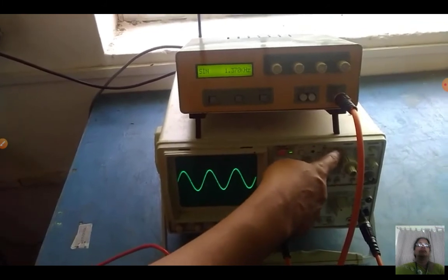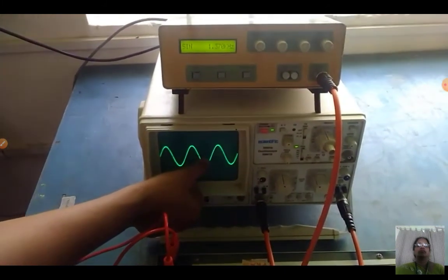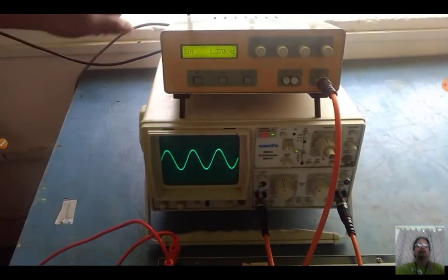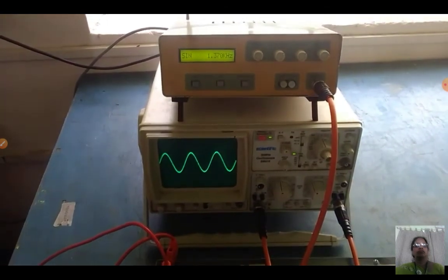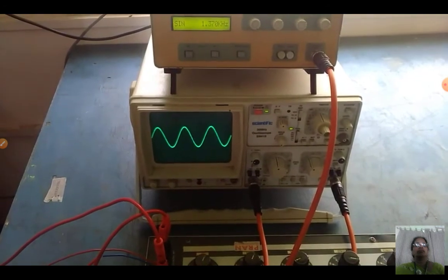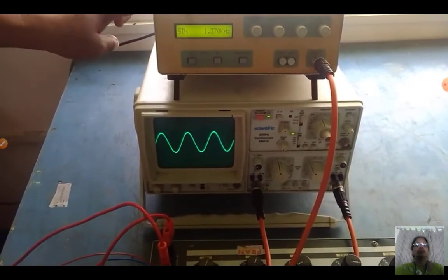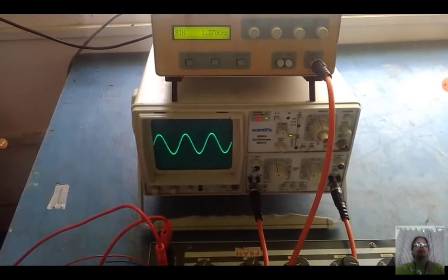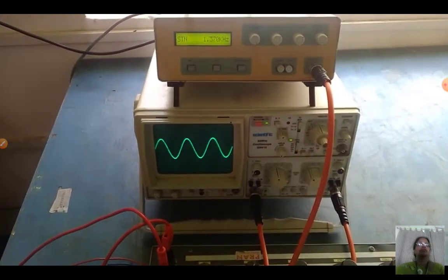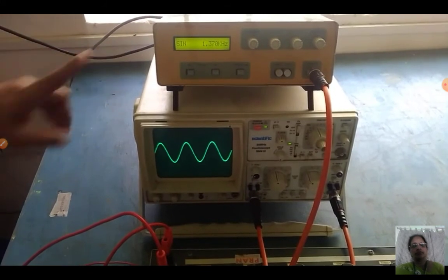That means milliseconds multiplied by the division. This is 1, 2 and then 3, 3.2. You can get the time converted to frequency. So like that you can take the readings from 1 hertz to 3 megahertz. Then you can take 10 to 15 sets of readings and note them down in the tabular column. The tabular column consists of frequency, output voltage and then gain. Input voltage should be constant at 3 volts.